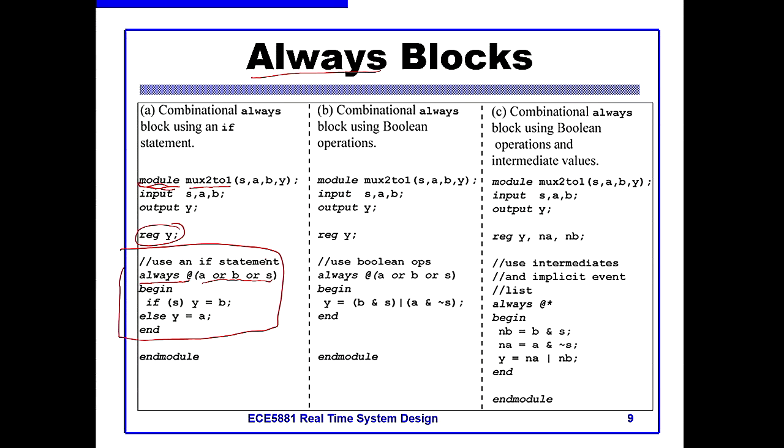Okay, so if, for example, S became 1 and it was 0 previously, you'd then look inside this block and you'd say, okay, if S is 1, Y should now take on the value B. If S is 0, of course, that corresponds to the else of this, and Y takes on A. So that corresponds with your 2-to-1 multiplexer structure. But you'll notice you've expressed that in terms that are behavioural, we call this behavioural description. So you can generate some statements that make a lot of sense to you as a designer, and then it translates that later into basic Boolean expressions that can be implemented.